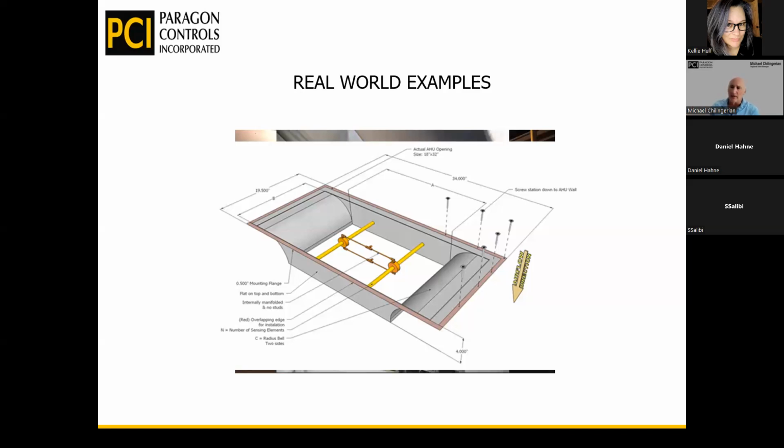So in a lot of cases, we'll have a rooftop unit, for example, and the frame size can be from 15 to 50 tons, just as a number. Well, that 15-ton unit is going to have the same size opening as the 50-ton unit. If we can decrease the area a little bit, we'll get the velocities up some and make the outside air damper work better, because instead of just cracking open and letting all the air in, it'll control a little bit better. So we do stuff like this with the sheet metal for our airflow stations all the time for outside airflow measurement.